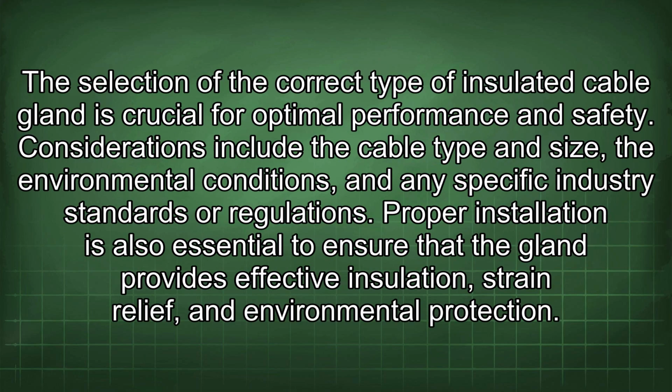The selection of the correct type of insulated cable gland is crucial for optimal performance and safety. Considerations include the cable type and size, the environmental conditions, and any specific industry standards or regulations. Proper installation is also essential to ensure that the gland provides effective insulation, strain relief, and environmental protection.